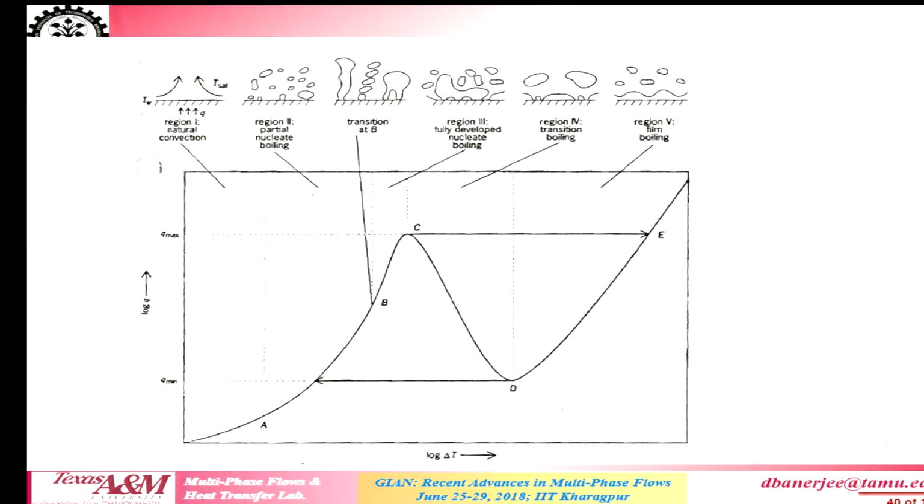So you have a mushroom shape because the two columns joined up, and the liquid that was trapped in between takes a mushroom shape. This superheated mushroom shaped column has a very high surface area, and that starts feeding steam, or vapor, at a very high rate into this mushroom bubble.